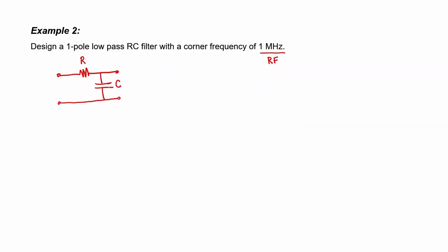Hundreds of picofarads. Now if the capacitor is too small, like say 50 picofarads or 100 picofarads, then that's not very good if you intend to build the circuit on a breadboard because the plate-to-plate capacitance on a breadboard is in that neighborhood, so we need to avoid that.